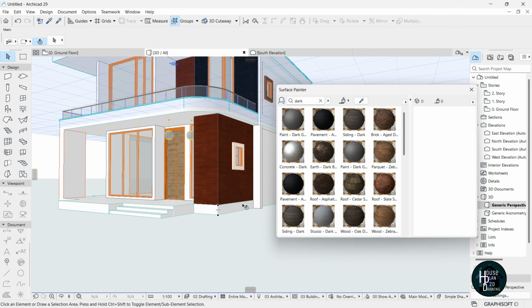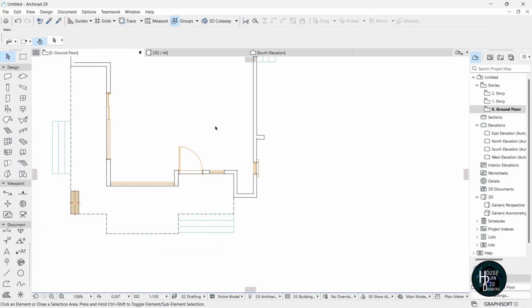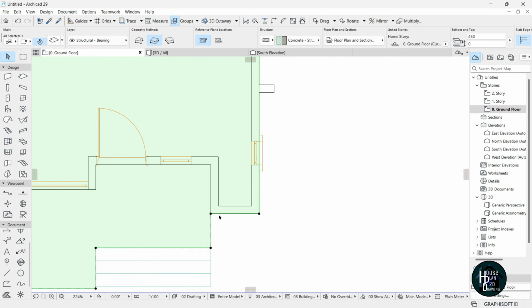You have to model the slab to look something like this. So we have to cut out this side and place another slab there, then model it. You see what I'm talking about by going to the ground floor plan. And let's select this slab here. I'm going to hold on this. I'm just going to click on this node and make sure I'm selecting the structure from polygon. Just cut it out to this side here.